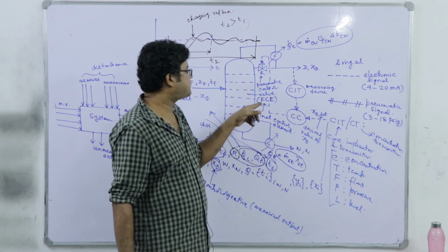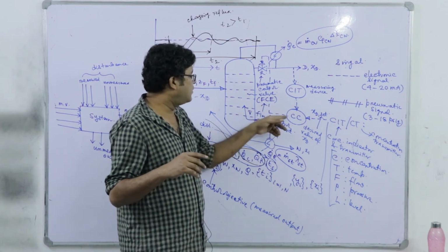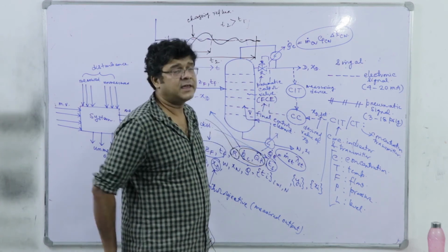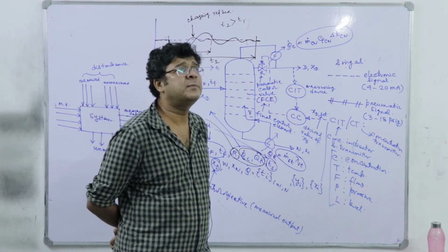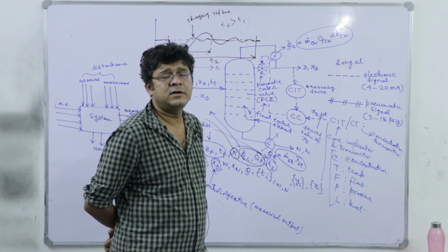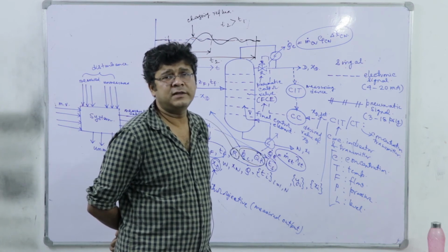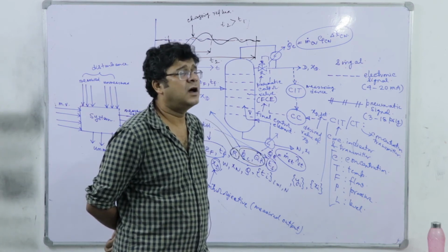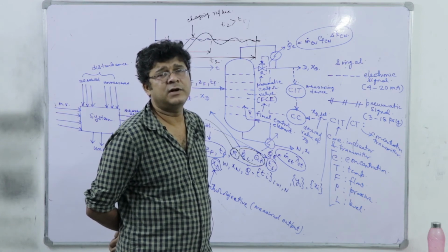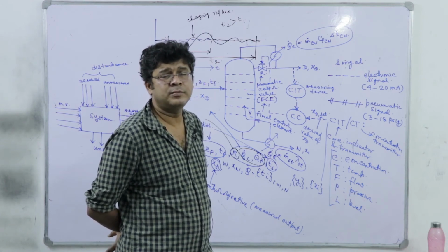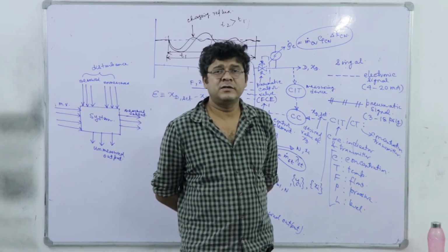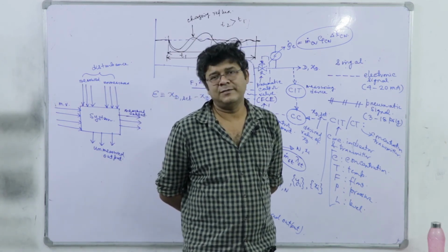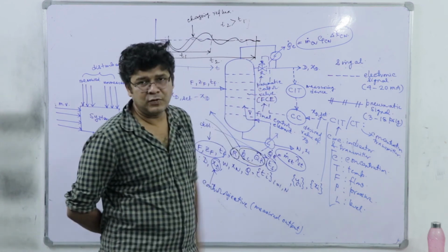So here the controller's decision in that specific case will be implemented via what? A switch, which is supplying current to the different lamps and lights or fluorescent lights, whatever are mounted in that room, right. So there the final control element is a switch, not a pneumatic control valve. Here it is a pneumatic control valve.